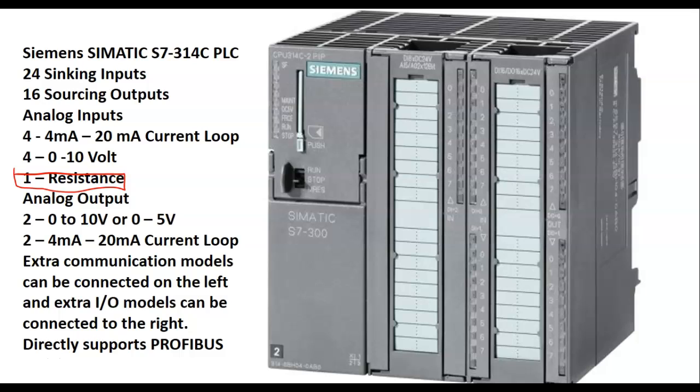What this means is we have problems trying to send voltage over distance. These are high impedance circuits, which means these inputs pull almost no current at all. So the PLC pulls current. The outputs are where all your current is. The higher the impedance or resistance of the circuit, the more likelihood for electromagnetic interference to interfere with your voltage. So EMI can change voltage if there's hardly any current involved.